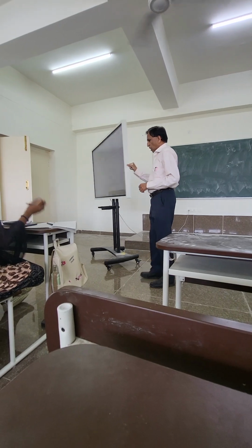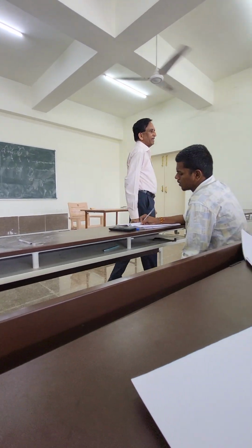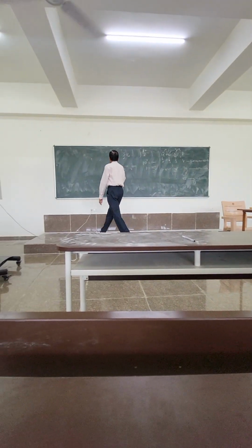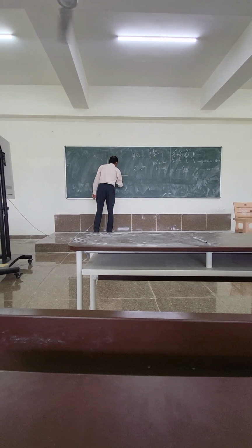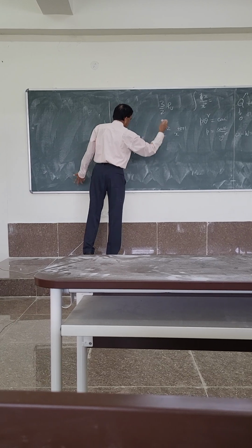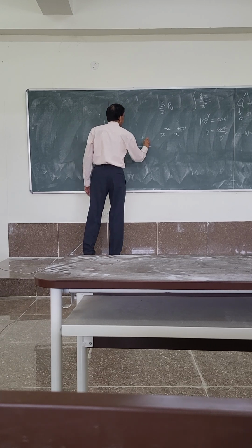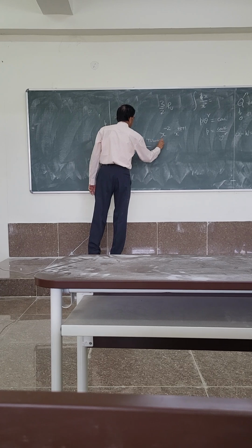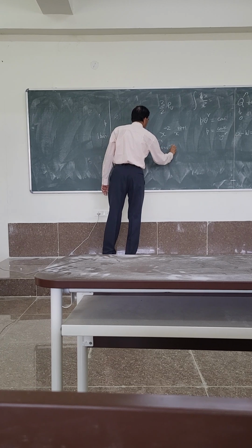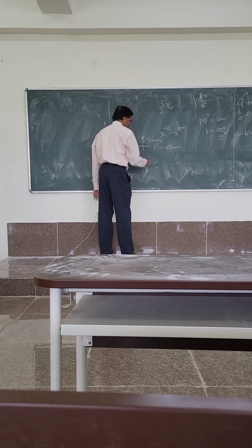Okay. Now I'm going to turn this off. I want you to calculate the isochoric work. The first one is the isochoric process. We don't know V yet, but I have given you the value of P as 1 bar, the temperature is 300 K, and RU is equal to 8314 joules per kilomole Kelvin. First, find V1.